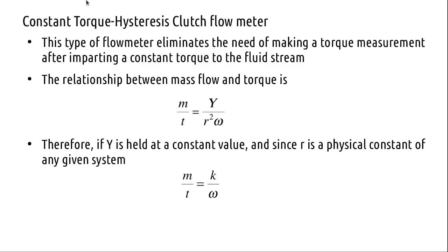So your clutch plate is coming in contact with your mechanism that transmits power to the wheels. Now in a hysteresis clutch, this contact will not be there. There will be an air gap, and you will be transmitting power by an electromagnetic coupling. That is the idea there. We have a figure there.